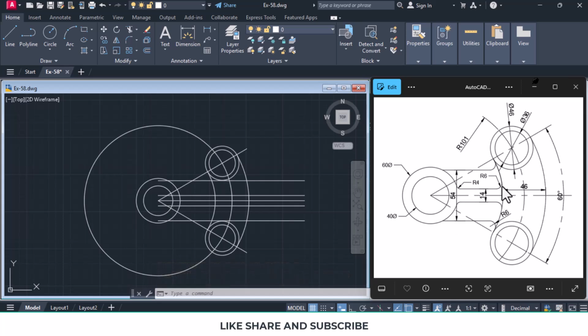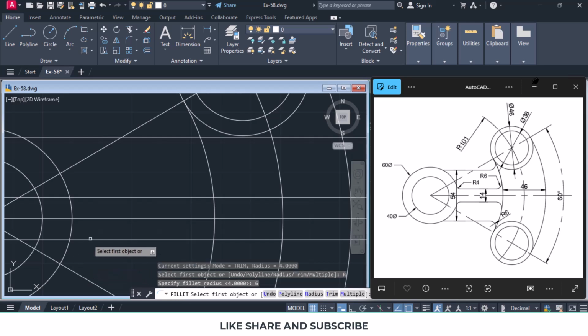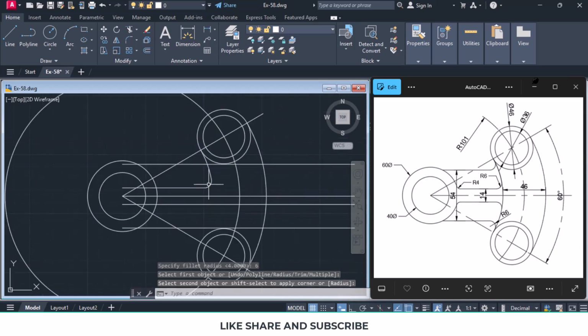Now we want to do the fillet. So this fillet we'll do first. This fillet is of radius 6. So we type F for fillet, R for radius, and we give the radius of 6 units. Hit enter. And then we click on the first line and then we click on the second line. So this is now filleted to a 6 radius.